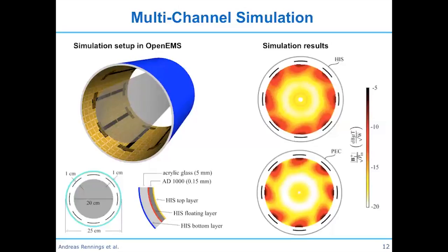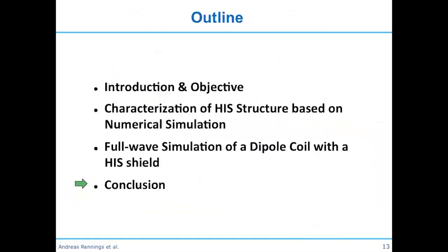You know, the gradient fields are also normal to that closed loop, and that would cause large currents to be induced. Another way would be to remove the ground plane and just keep the top metal layers, but that would involve a redesign of the HIS unit cell. That will be one of the next steps.